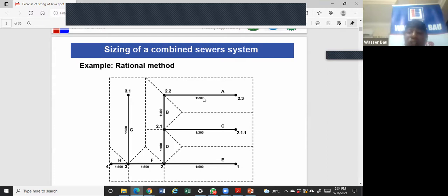When your surveyor is working, your surveyor should take the coordinates and the spot heights, depending on what you agreed, 25 meters, 50 meters, 100 meters, whatever it is. We have to take it along the network, along the major networks.